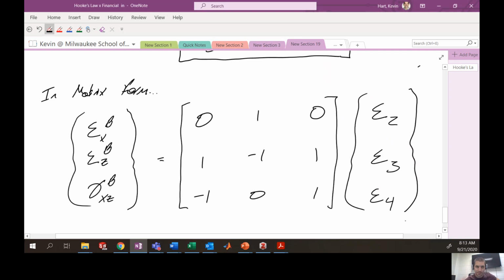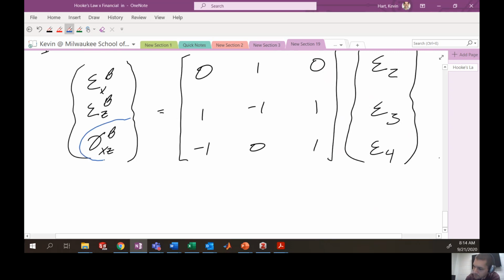So this transformation matrix is given to you in the lab. I think people were a little bit confused about where this came from and what it represents. But hopefully, through this lecture, you understand that strain transformations are required, along with some knowledge about how the strain rosette gauges work, to ultimately get the information about the strains at this particular point of interest. Okay, so after executing this, you should have strain xz at B, and you should also have tau xz at B from combined loading equations.